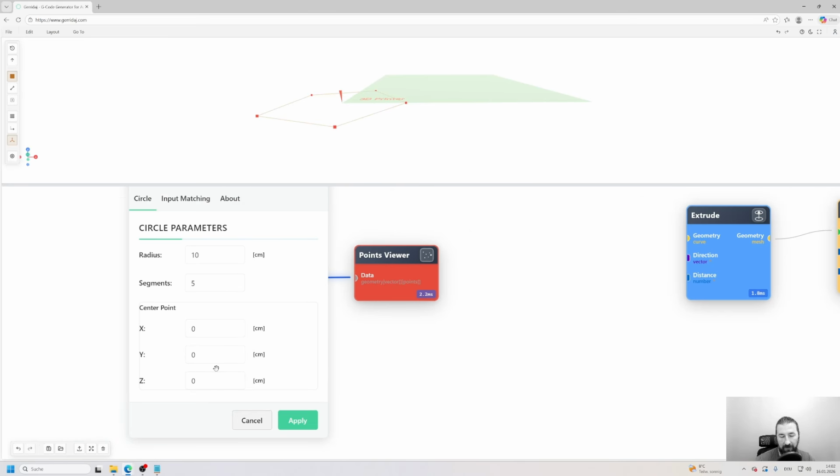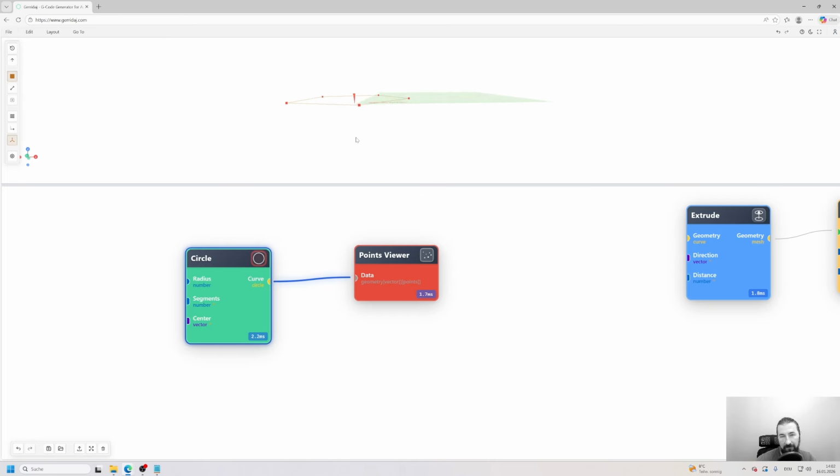So if you haven't set a Z offset on your machine, then you can just put your toolpath directly at some different Z. So I can put it at 1 centimeter height. You see, and you could even put that into your machine, and the machine will execute this command. The filament will not stick to the bed because it's too high, but it will just drop onto your bed. Of course, you see your zero point of the machine is here now in the middle of the shape. So this will not work. You need to move the shape into your print area first.